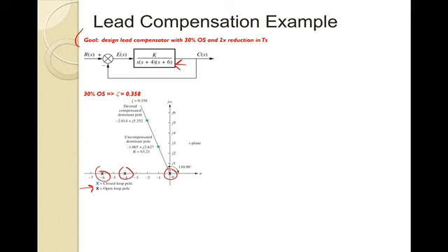So if I know I want a 30% overshoot, that immediately says I can draw my damping line at 0.358 and then look for the desired poles in my system. Relative to our uncompensated settling time, I can use this formula as shown below, and sweep a value to find the settling time given the damping, which I know, and the natural frequency.